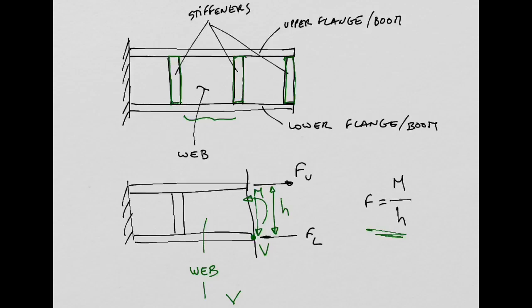Okay? We are not going to develop buckling here, we don't have time, but for example, the buckling of a plate is strongly dependent on the width and height of the plate, okay? So if you have a very large width, the buckling can happen for much lower forces. So by putting these stiffeners here, basically we are reducing the width of the plates so that we can control the buckling better.